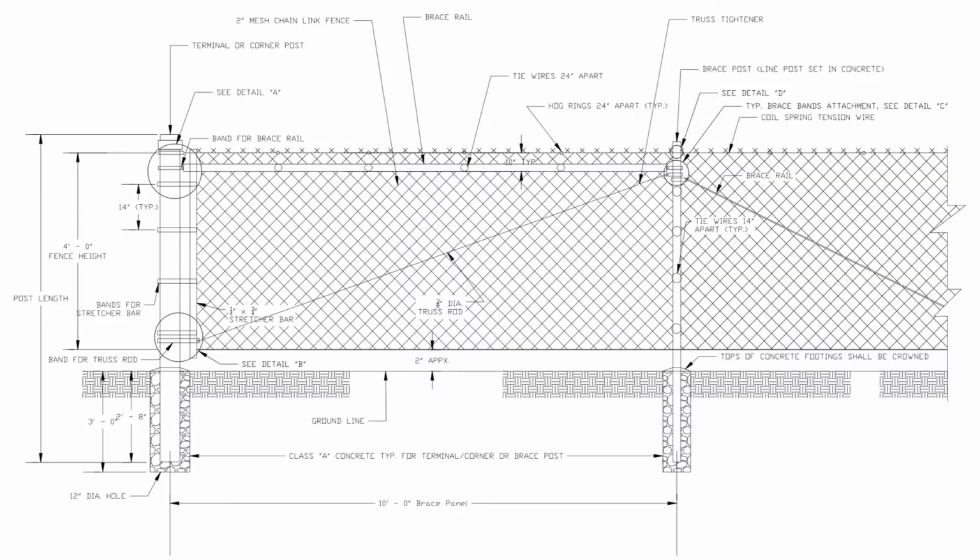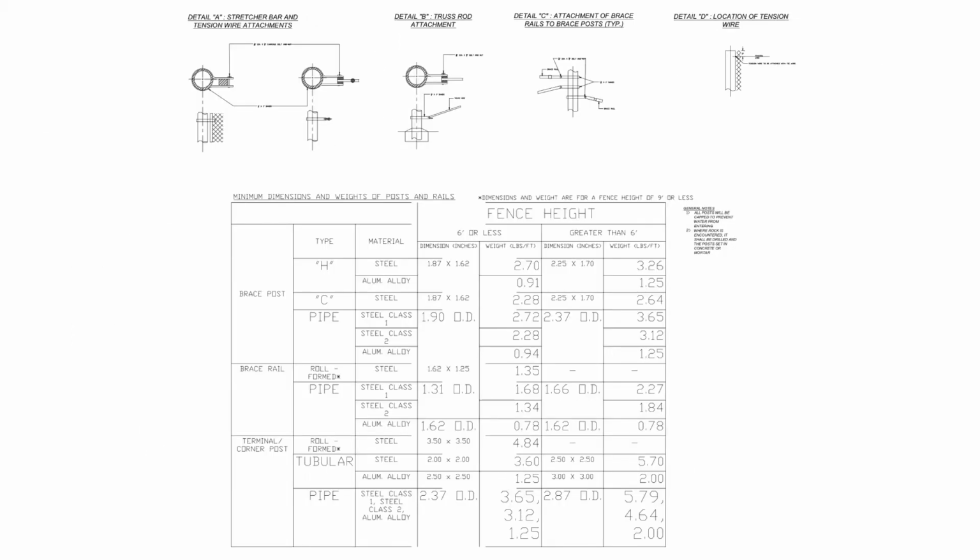We presented to the town of Manchester 3 alternatives to replace the stone wall: a timber fence, a concrete wall, or a steel fence. After presenting each stone wall alternative based on their cost, appearance, longevity, and ease of installment, our sponsor decided they wanted the steel fence due to its durability. As you can see in the final design, we have provided to the sponsor the plans for creating a steel chain link fence with the fence posts anchored in preformed holes to provide foundation to the fence. This will be implemented at all areas of the collapsed stone wall.